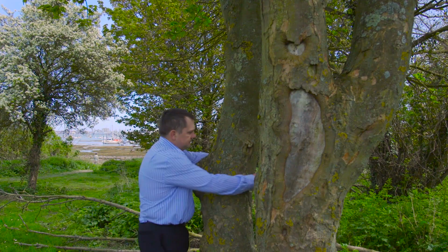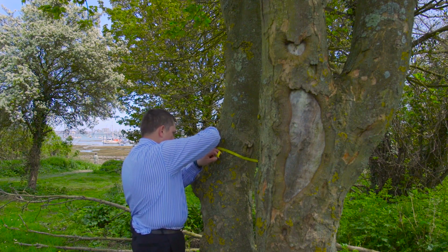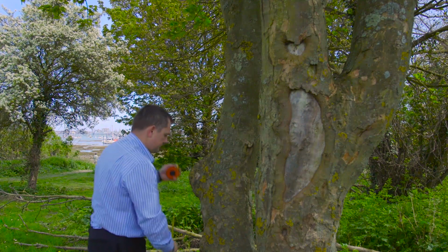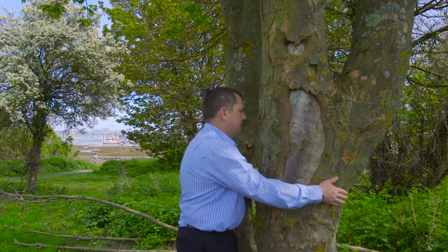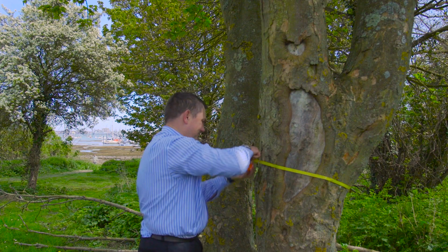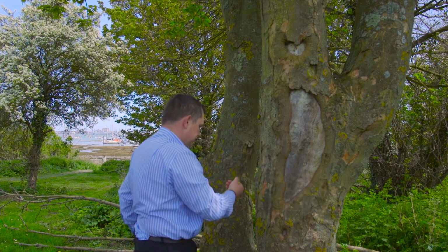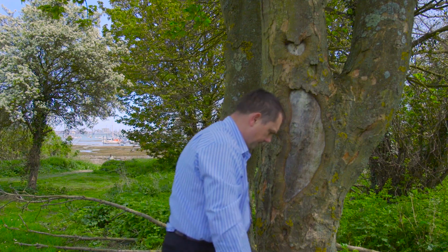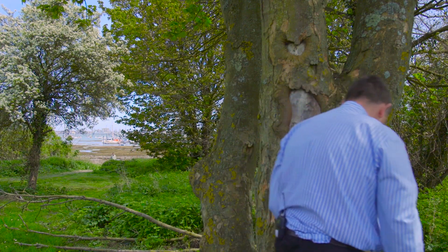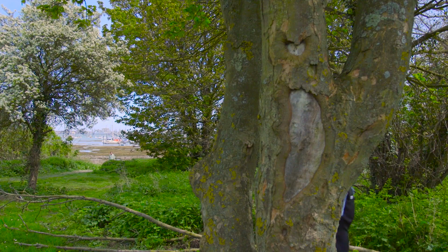As part of a BS5837 tree survey, a basic tree condition assessment should also be undertaken. In addition to that, accurate measurements of constraints posed by any trees on the site or adjacent to it but close to the boundary should be recorded and plotted on a tree constraints plan. The main constraints are the root protection area, the canopy and shading from the trees. The RPA is 12 times the stem diameter at 1.5 meters.